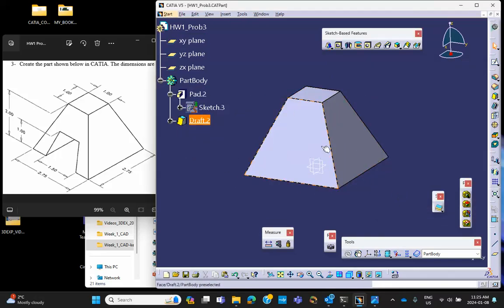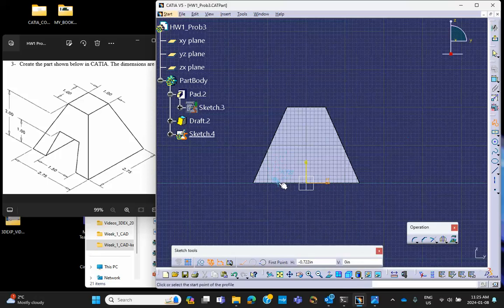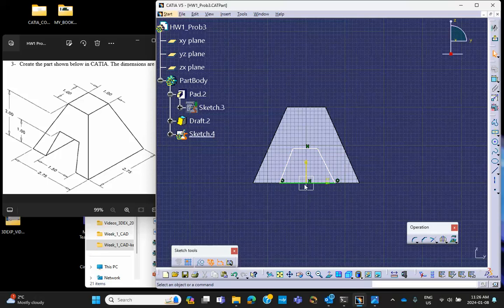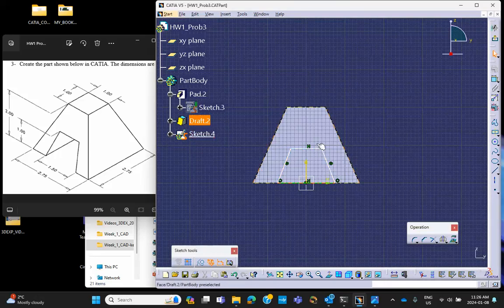So you're almost there. The only thing is that I'm going to have to make this cutout here, and unfortunately for this cutout, something is missing. This angle or some other piece of information we need is missing. Okay. So here's what I'm going to do. On that vertical plane, I will sketch a profile like this. And I'm going to make it nice and symmetric. Control that, control the middle axis, so it is symmetric. All right, good. And that height is going to be 1 based on the drawing, 1 inch from here to here.